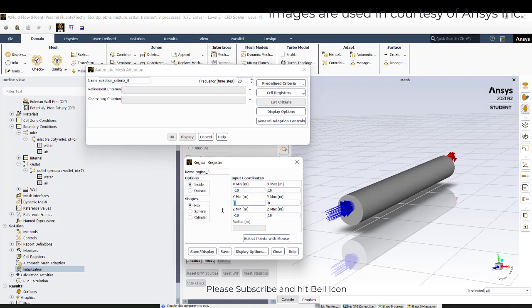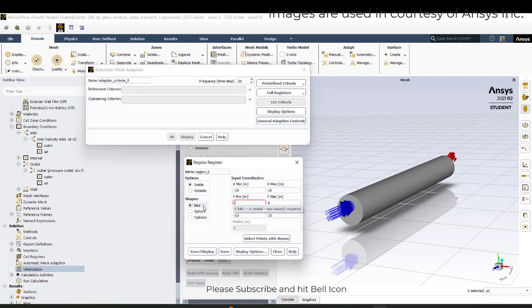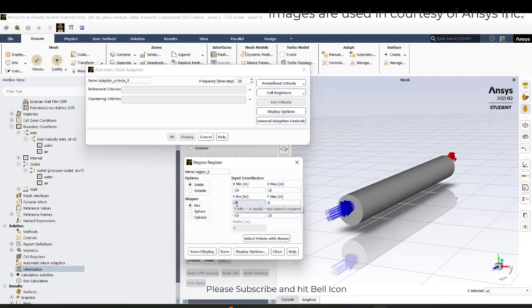But for y you need to have a certain value. So for y we can just check here. The radius is 4 mm. So here in the y negative direction it is -4, and in the positive direction 4. So for the negative direction we will enter -4. The unit is in mm, so this is 0.004, and here it is minus 0.001.